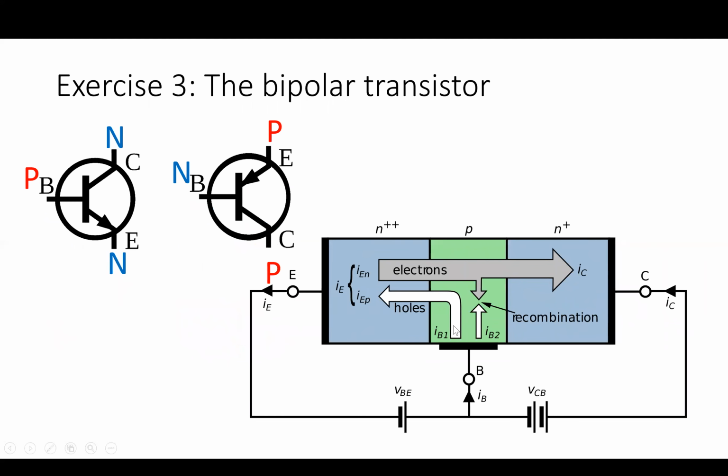When you overcome the thermal barrier to conduction of this junction by applying an adequate bias, something greater than ½ volt between the base and the emitter, then current can freely move from the base to the emitter. But having demolished the thermal barrier, electrons are free to diffuse into this region here, where they feel the huge electric field from this reverse bias junction. And so if this transistor is designed well, most of these electrons are just swept up by the collector, which is why it's called a collector.